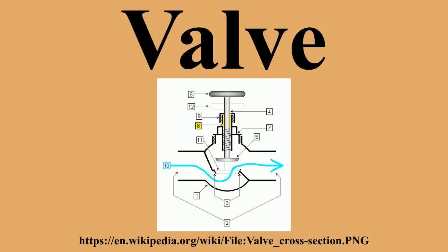Valves whose disc is between the seat and the stem, and where the stem moves in a direction into the valve to shut it, are normally seated or front-seated. Valves whose seat is between the disc and the stem, and where the stem moves in a direction out of the valve to shut it, are reverse-seated or back-seated. These terms don't apply to valves with no stem or valves using rotors, gaskets or mechanical seals, or packings, used to prevent the leakage of a gas or fluids from valves.